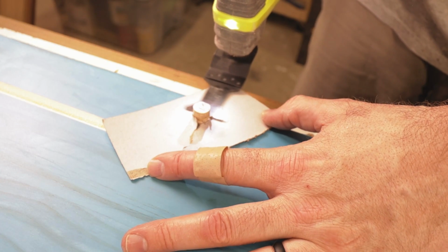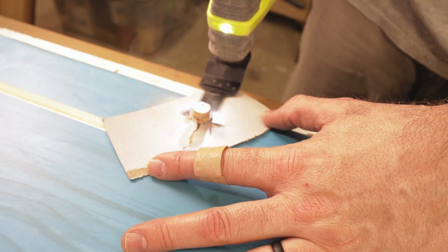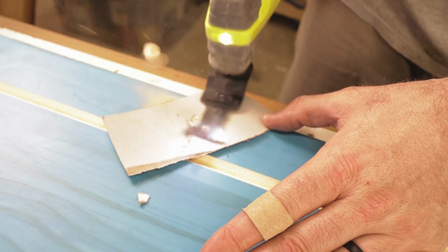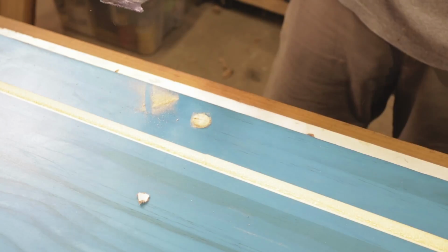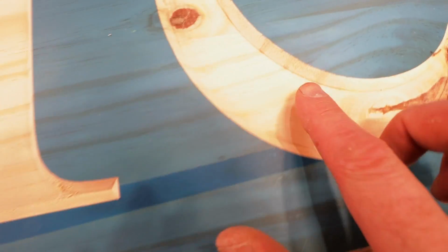Lastly, I glue in the dowels and cut them off nice and flush. And as you can see now, this sign, it was made out of pine. And one thing I have to mention is make sure that you have a really sharp 90 degree V-bit blade. It really left some fraying, and I'm going to have a little bit of sanding to do. So when you're using these soft woods, just make sure you have a sharp blade.